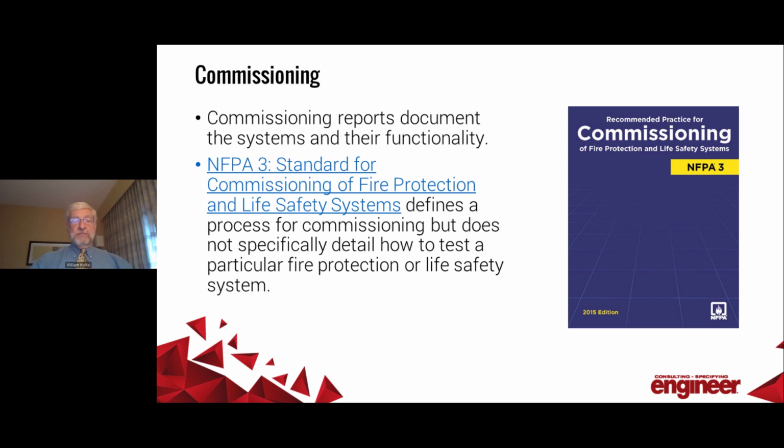senses a condition. NFPA has two documents that I'm going to make quick reference to. NFPA 3 is a standard on commissioning. It's not a technical document. It talks about a process, the commissioning process, and how we should go about it. By the way, commissioning doesn't start towards the end of the project. It should start at the very beginning. Part of this is to develop a test plan, not just for the initial commissioning, but also for the frequency at which we need to reevaluate whether this system is operating in its entirety.